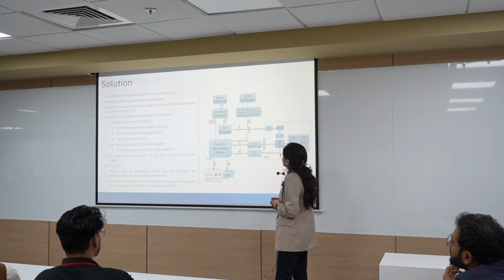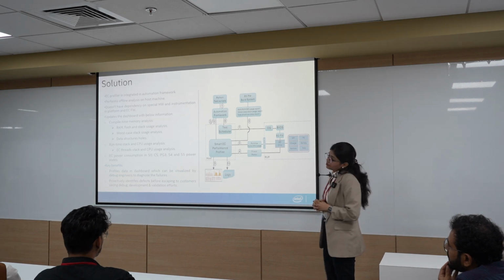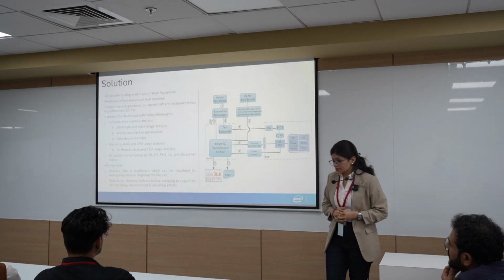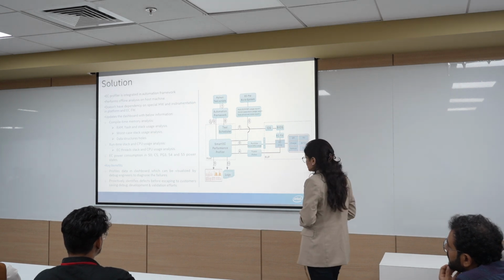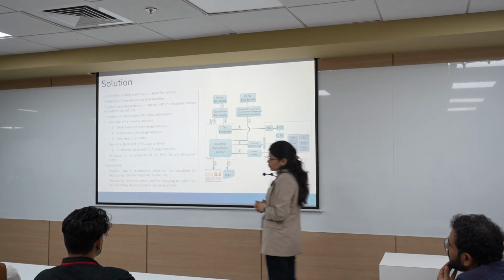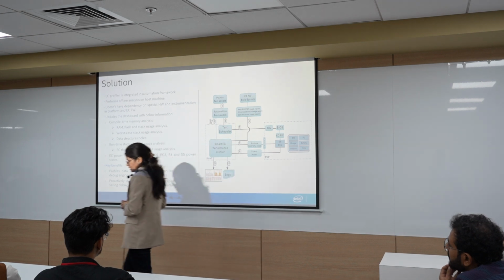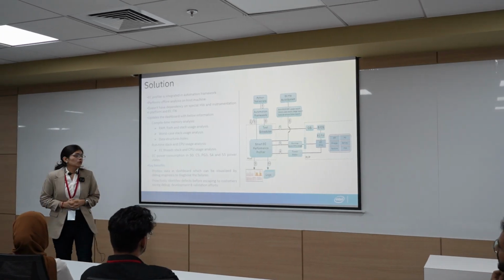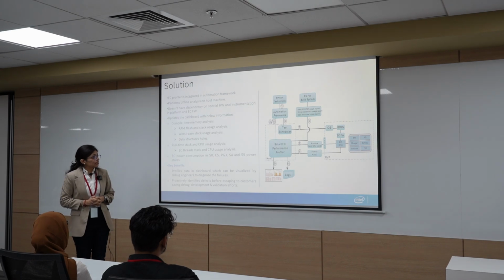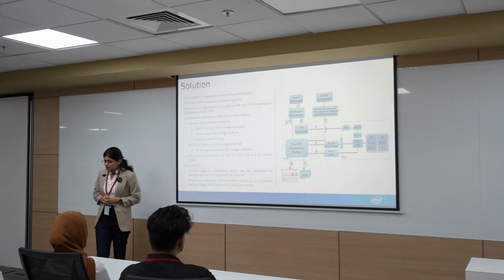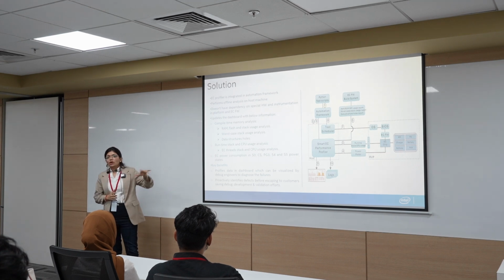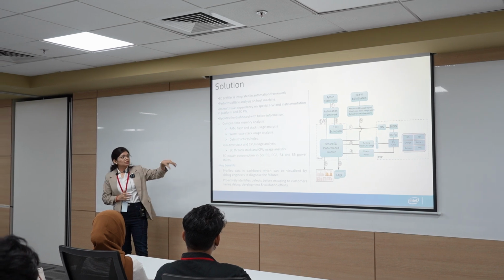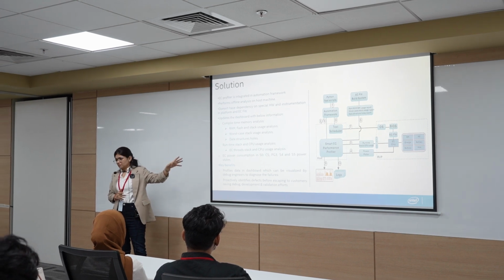As you see here, the first point is the EC firmware build, once your application is built. And we have the automation framework. Another point is we have integrated this tool into our automation framework, so we can run it overnight also. So first step, the EC firmware application build happens, and that is a Python run. We have the Python script already, which has the command necessary to get the pahole and puncover data.